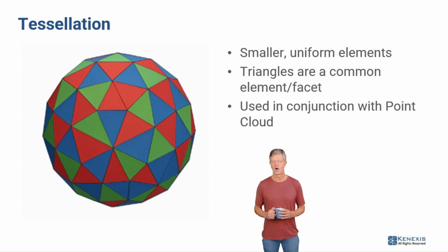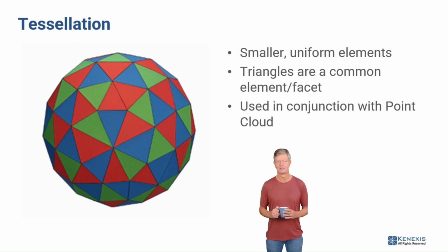Once a point cloud is acquired via a scanning process, this point cloud can be turned into a 3D object using the process of surface reconstruction, or skinning. Through this process, the gaps between the points are filled in to create a watertight, usable 3D surface. Tessellation allows this reconstruction to occur by connecting the points with facets, such as connecting 3 points to form a triangle. Another common method of tessellation uses cubes as the elements rather than triangles. This application is often seen in computational fluid dynamics, or CFD.